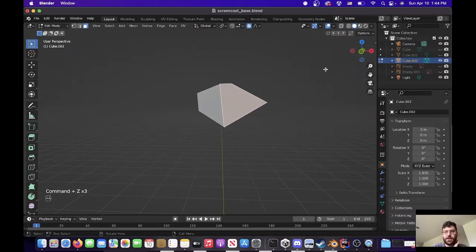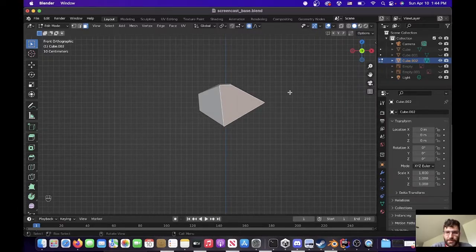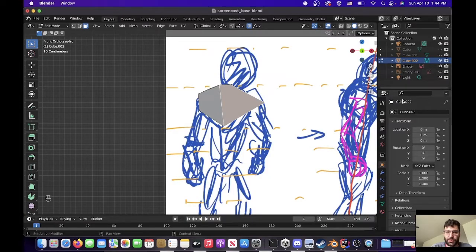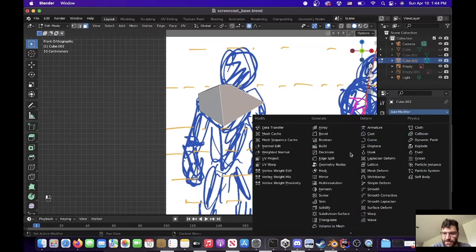And so here's one other thing that I was going to bring up before, but it didn't quite make sense yet. Our humanoid has something called bilateral symmetry. So we want the left and the right side to look the same. This is not symmetrical. We could painstakingly make both sides symmetrical if we want, or we can use something in Blender called a modifier, which is down here, this little wrench, this whole big toy box of things you can do to your vertex data. In particular, we want something called a mirror modifier.